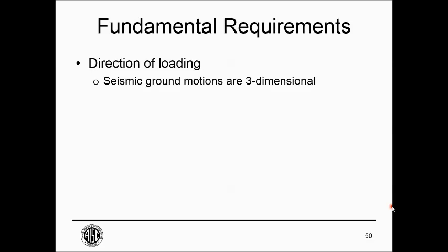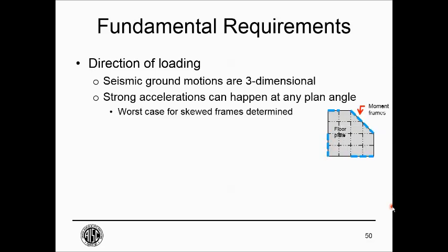Direction of loading. Remember that seismic ground motions are 3-dimensional. They certainly operate in both plan dimensions at the same time. Since those horizontal forces can happen at any angle, it's not enough to take a building like this and just analyze in the X and Y direction and leave it at that. This skewed moment frame that I'm showing here, we have to consider what's the right design case for that skewed moment frame.